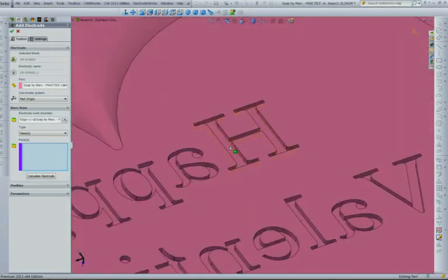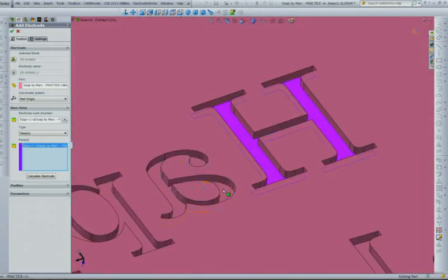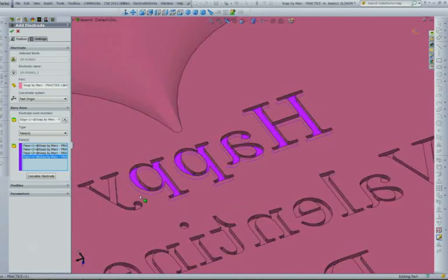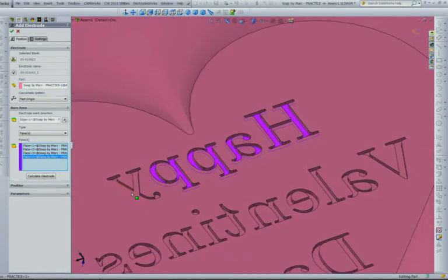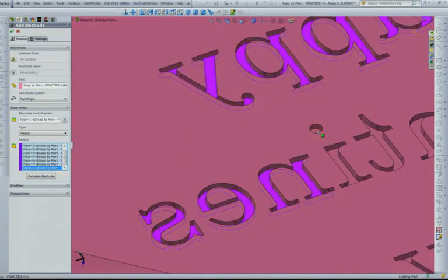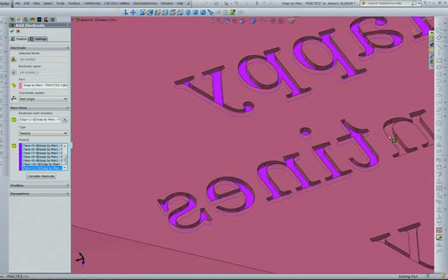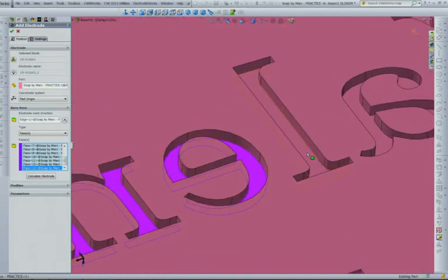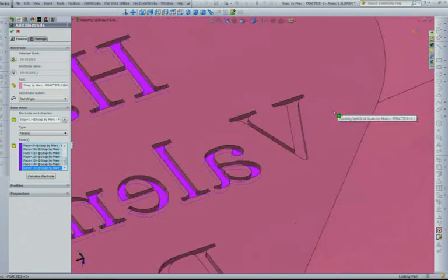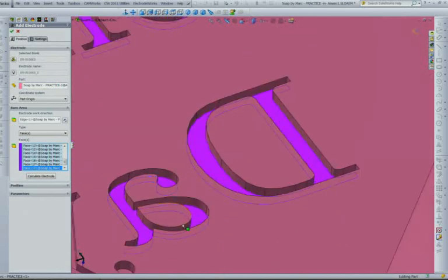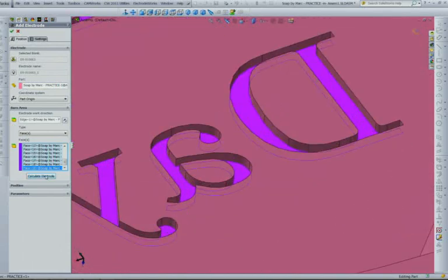And then what I want to do is go ahead and select the faces of the portion of the part that I want to burn. This might seem a little tedious, but remember that when it comes to electrodes, there's oftentimes when you want to burn one face and not another. So this allows you to select the faces individually. And now that they're selected,